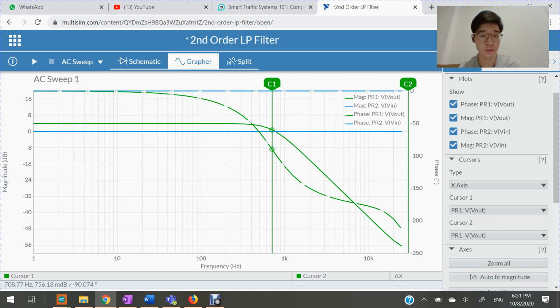And this is the cutoff frequency, from which we can see that before the cutoff frequency, the voltage gain is at its maximum, which is around 3.94, and slowly starts to decrease as it approaches the cutoff frequency. After it passes the cutoff frequency, you see it drops dramatically, about negative 40 decibels per decade. And yeah, so this is the Bode plot shown by the AC sweep.